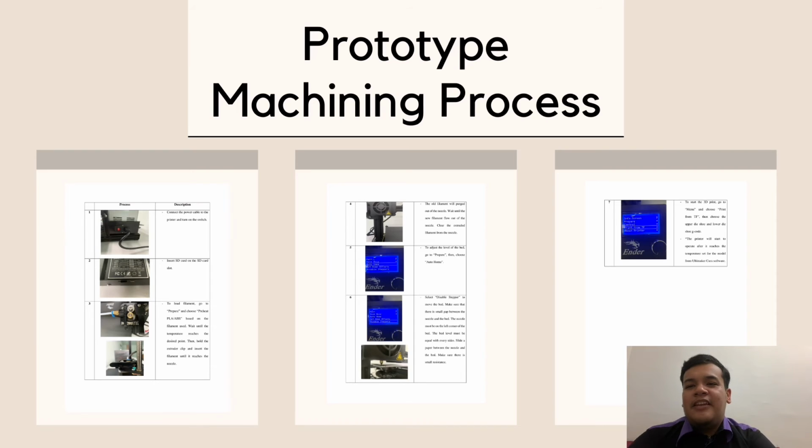These are the machining preparations before the prototype is printed. There are hazards that need to be focused on when using this machine, such as the high temperature nozzle, which can cause severe injury, hot filament coming out of the nozzle, and mechanical hazards from moving parts.